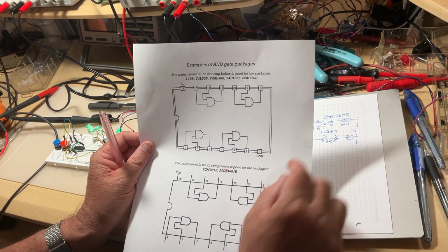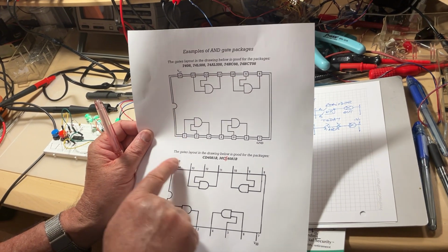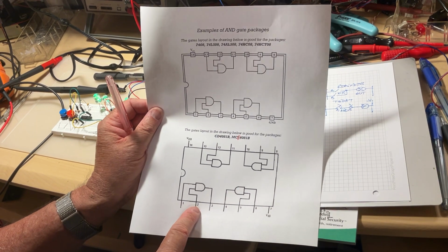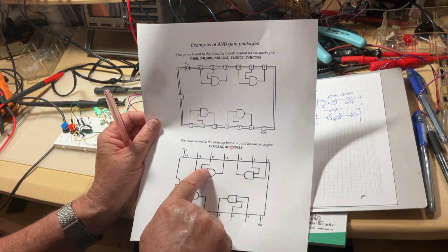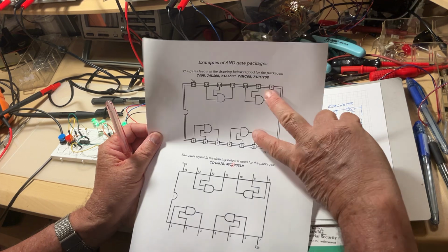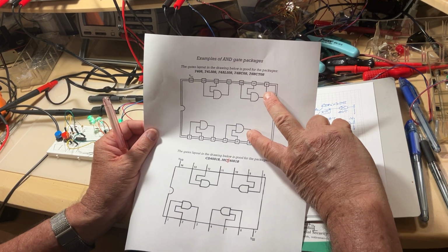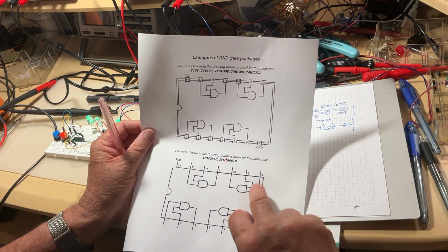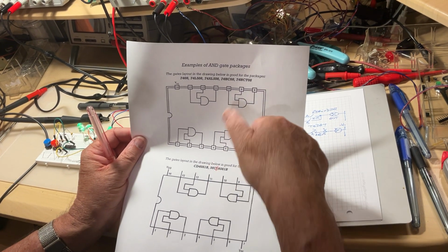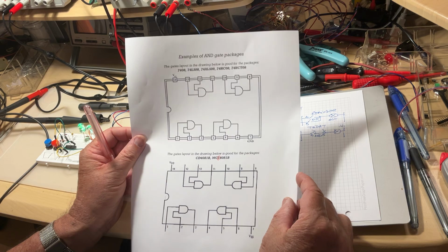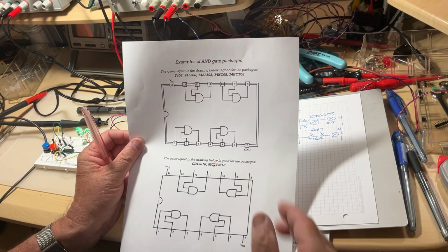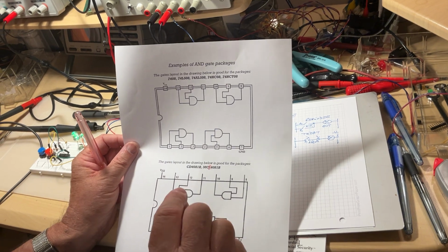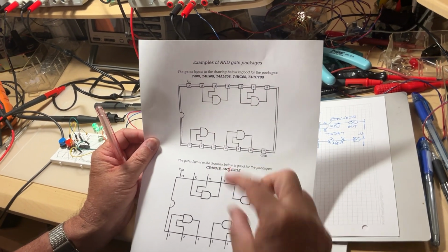If you can take a look, in the TTL package, this gate here I put my finger on is in the same position as the one in the CMOS. And the same about the one in the top, in the same position, but the other 2 ones on the right side, as they are arranged here, are arranged the opposite way, reversed. So this is why the packages are not interchangeable. So you have to be very careful when you use this one and that one, because even if both perform the same function, the packages cannot be replaced one by the other.